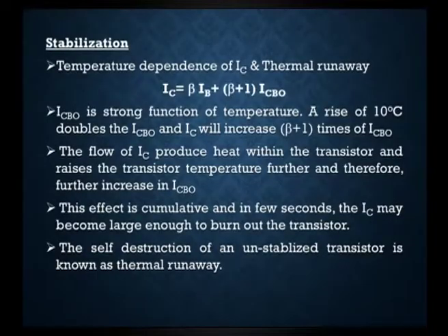This effect is cumulative, and in a few seconds the IC may become large enough to burn out the transistor. So, IC should be kept minimal so that it does not burn out the transistor. The transistor may be damaged due to high collector current.